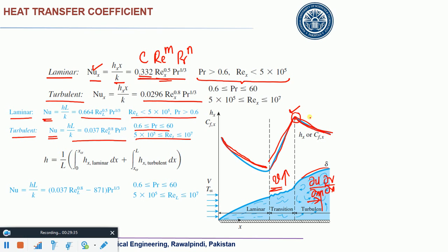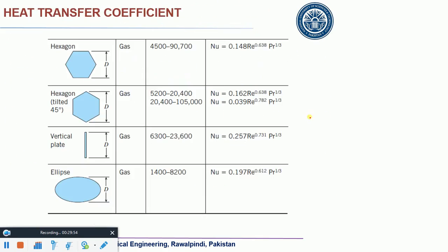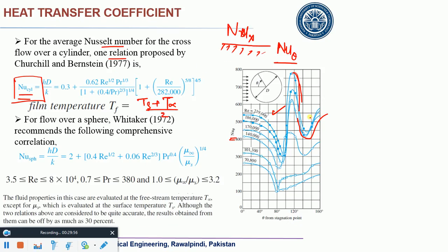Come on, you know that. Yes, the temperature gradient decreases. Due to what? Thickening of the boundary layer. As you move along the plate, that boundary layer gets thicker and thicker. So this is the same reason behind those variations. So it drops due to thickening of the boundary layer, right?